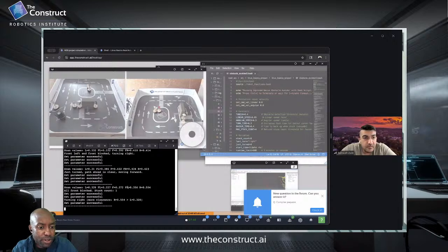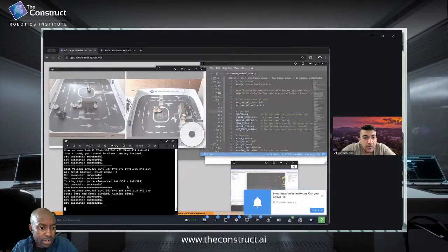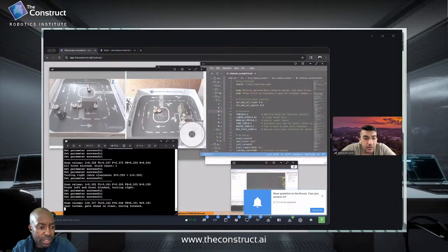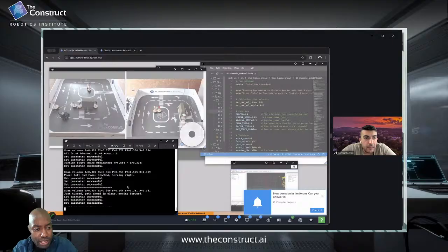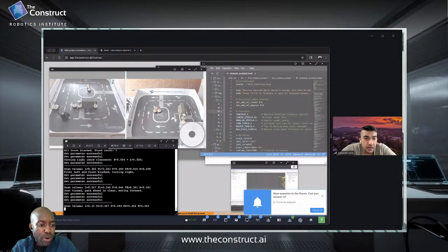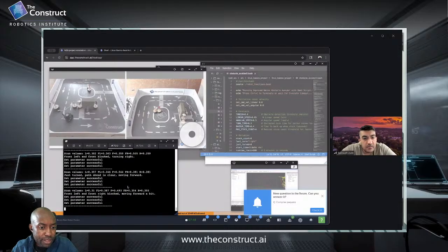Yeah, we could say that because, well, the 0.3 just gives it enough distance to stop, right? And there's also the control loop that checks that the robot has reached 0.3, right? So how long does it take for that control loop to respond to stop the robot if the 0.3 threshold has been reached? So there are a couple of things being taken into consideration. But you also want your robot to turn with enough room for it to rotate, because it's got things that extend to the left and to the right of the laser scan sensor.